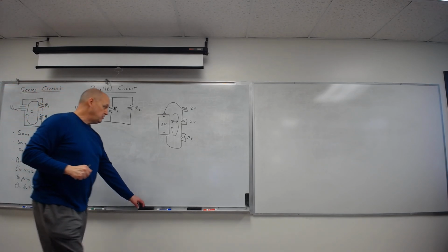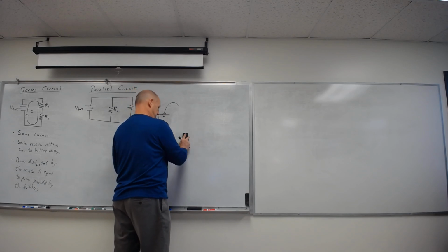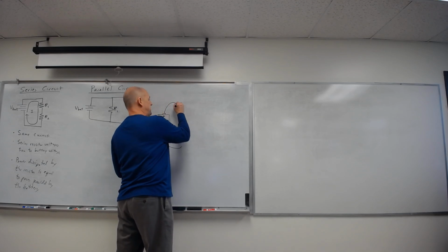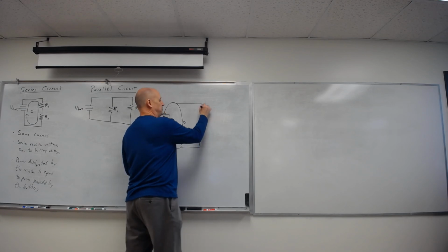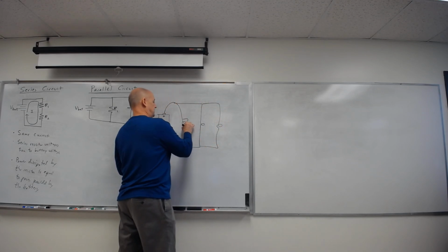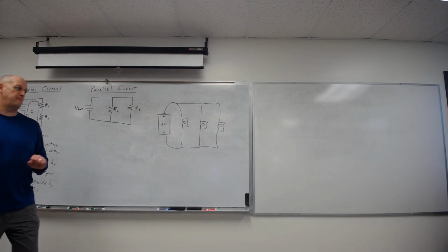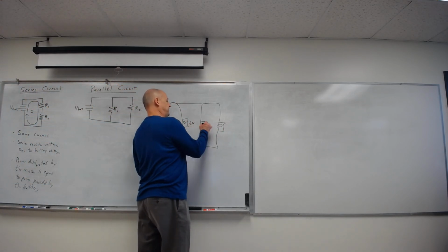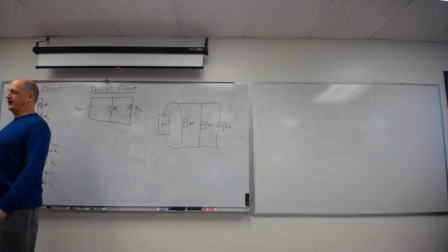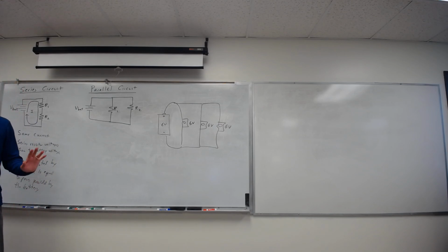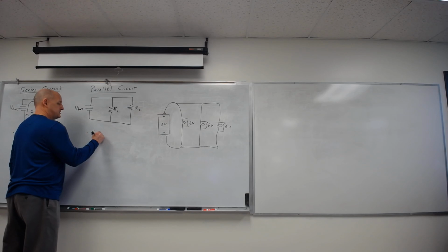So in the lab, you built one where you took these light bulbs and you connected them all in parallel. This is the one that caused the most trouble for most people. Measuring everything. So if you hooked them up, every one of these got 6 volts. You probably saw when you actually hooked them up that it pulled down the battery to about 5.5 volts, but they're all the same. Same voltage.